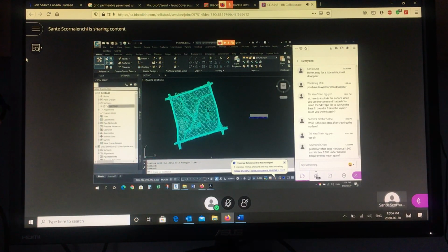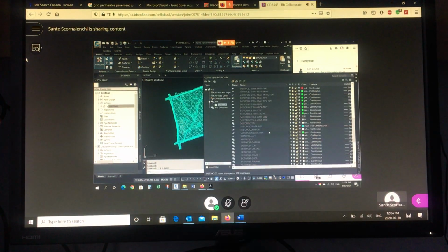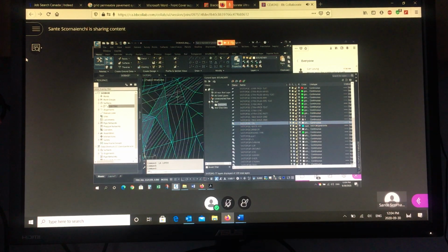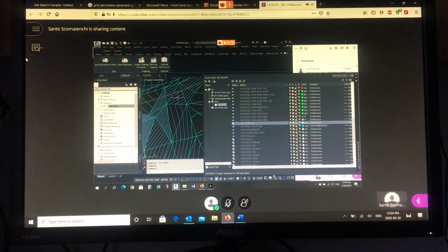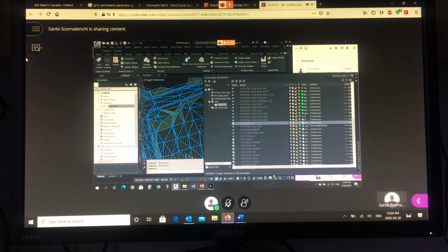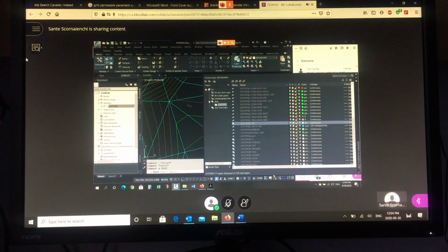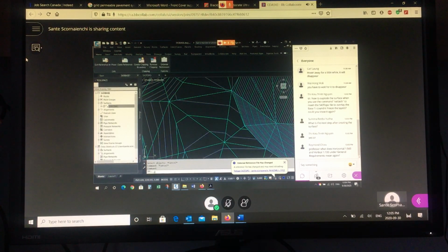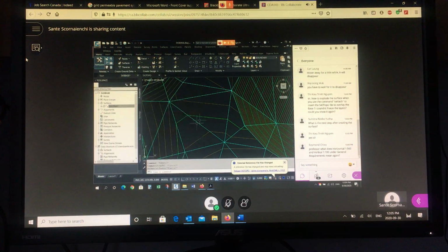Okay? I'm going to go back to my layer control. Watch, you're going to see two of them at the same time. If I go to 10 and I thaw it, okay, this is a view of the surface through the X reference function. This is the style of the shortcut version of that surface. So there's actually two things here, right? If I go to erase, there's two items. Right? Don't erase anything. See how there's two things? This is the X reference, right, the external file.